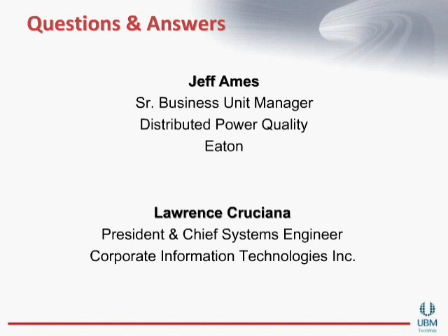Typically I'll take UPSs, for example. If you're starting to see a lot of hits where your UPSs overnight are going onto battery, and you print out a report at the end of the week, you come in during the day and you didn't realize any of that has happened because your UPS recovered and doesn't look like anything's going on. You can spot those issues before they happen, whether it's with your power quality infrastructure, your building power infrastructure, whatever it might be. It gives you a physical record that you can go back to, to help yourself, your support staff, or again outsourced third-party staff to really identify what issues you might be having with your physical power infrastructure.